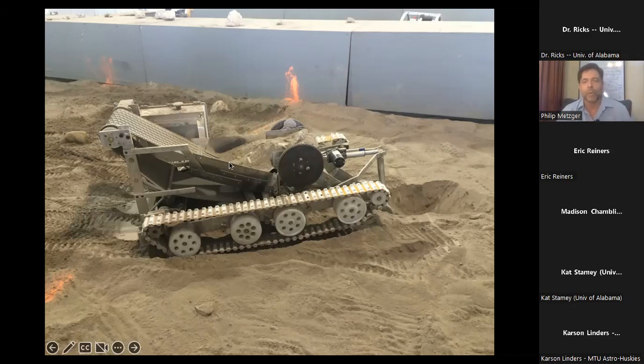Okay, so track systems, when you steer, you inevitably scrape some dirt between the wheels and the track. And then as you drive, that dirt gets pulled between the wheels and the track. That tensions the belt. It puts side loading on the wheels at the 2 ends. It side loads those axles. And it can lift the tracks completely off the wheels. We've seen tracks break under tension. We've seen the wheels stop turning because of the side loading on the axles. And also you've got so many little joints in those treads that get dust in them, which builds friction.